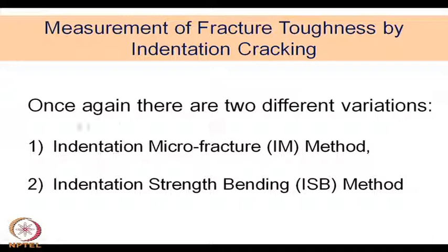But if the load is more than that, then certainly cracks will be generated, and those cracks can also be used for fracture toughness measurement, because these cracks can be allowed to grow further under flexural load, and from that one can make an estimate of the fracture toughness.